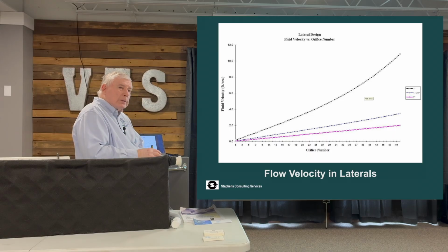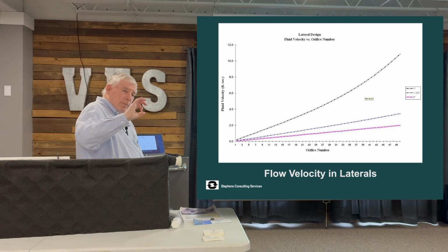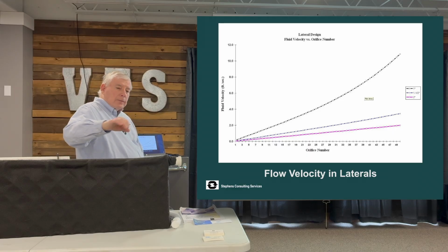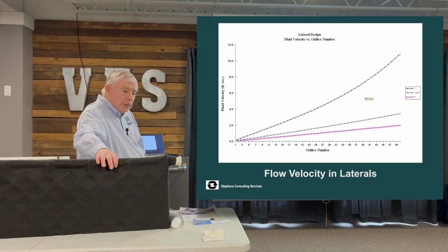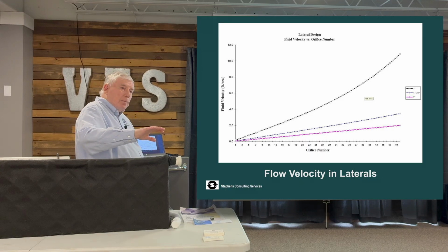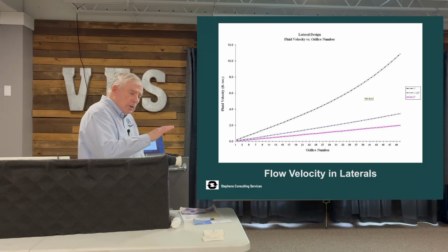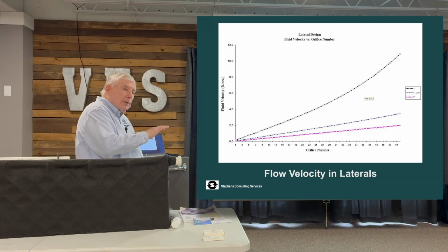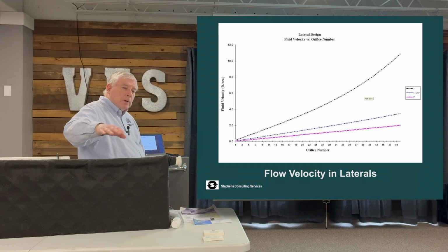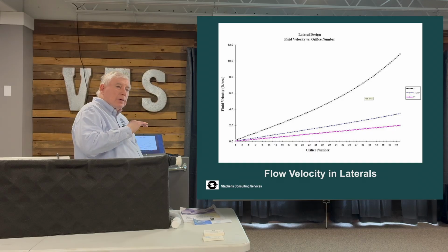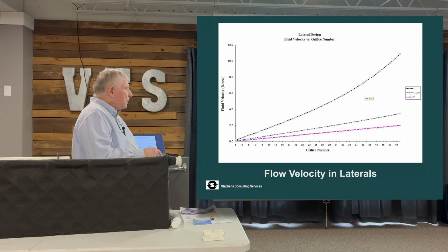If you use a 3/4-inch pipe, to honor that 10%, you'd have to have a shorter lateral to keep equal distribution. If you got a 2-inch pipe here, you could put probably 30 or 40 of these together instead of 18 with a bigger pipe to maintain equal distribution, but you would get very, very low velocities in that.